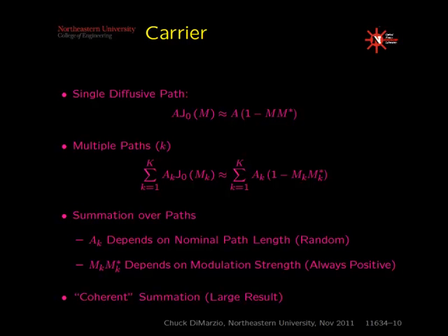It's not completely random in phase. The result is then that these will, in some sense, add coherently. If I can mix the signal ultimately with a reference wave that goes like A sub k, I will end up with a number which will be definitely negative, and I can then average over as many paths as I want, and that number will keep increasing, and it will increase now linearly in the number of paths rather than like the square root.